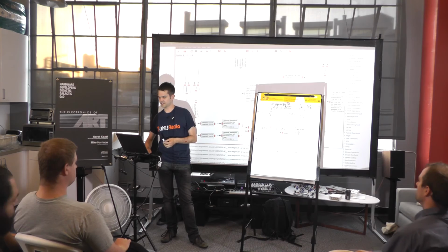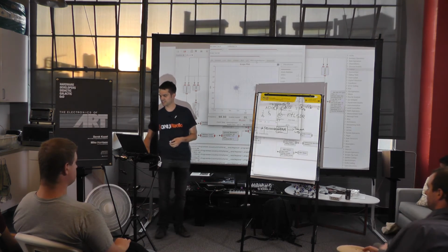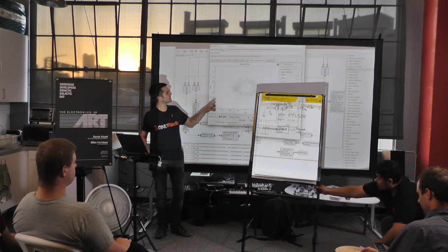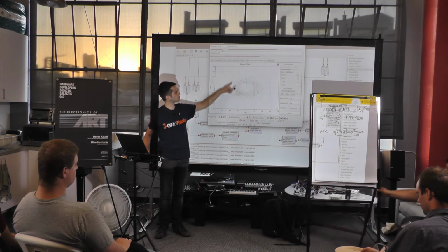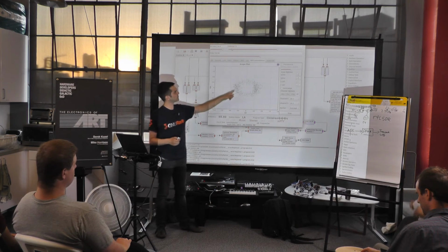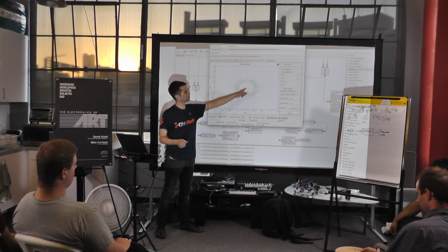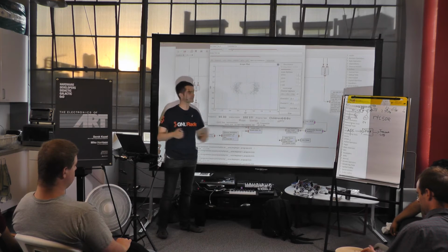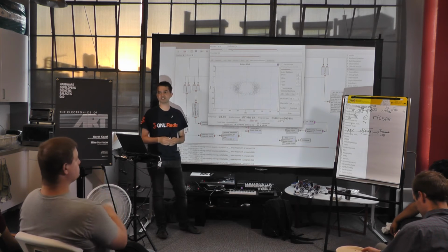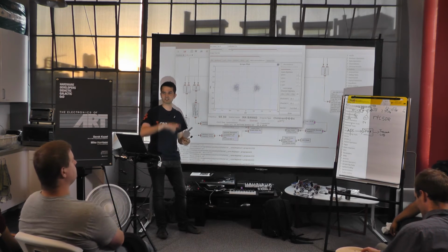Yes, absolutely. So if we go back to this constellation map, you can see here it's both losing synchronization and it's getting noise, and so it can tell that there's a signal there because we're not sitting at just 0. So there's stuff there, but this isn't a very good receiver, and so it partially ends up losing track.